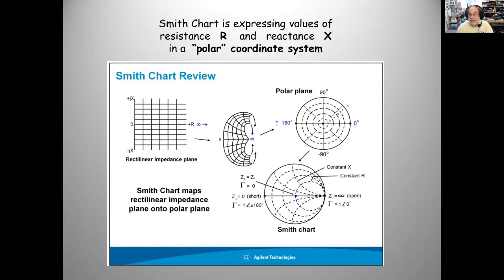With an antenna, we can't quite think of it that way, can we? What is resistance in an antenna? Well, the feed line comes up, and if you put a voltage across the feed line, you get some kind of current. If you take the ratio of the voltage to the current at the feed line, that's the resistance. So it's a practical definition of the word.